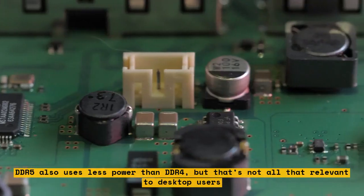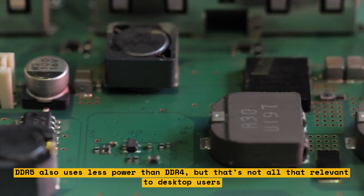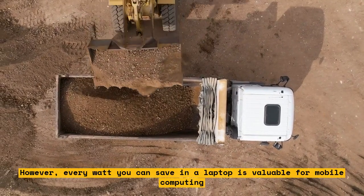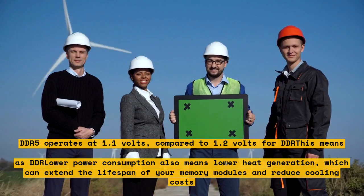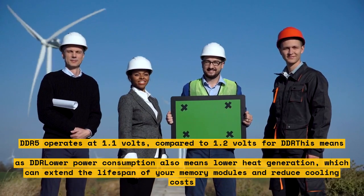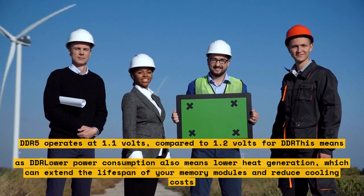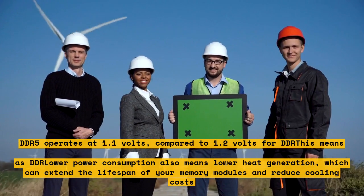DDR5 also uses less power than DDR4, but that's not all that relevant to desktop users. However, every watt you can save in a laptop is valuable for mobile computing. DDR5 operates at 1.1 volts, compared to 1.2 volts for DDR4. This means that DDR5 consumes about 8% less power for the same performance specs as DDR4. Lower power consumption also means lower heat generation, which can extend the lifespan of your memory modules and reduce cooling costs.